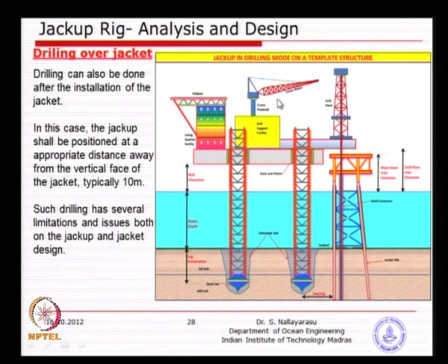So that is where, invariably, if you have a 15 meter reach, you will see that this location will become 6 meters, because you will occupy half the leg size plus the cantilever and all those things. Finally, the clear distance available between the pile and the leg could be only 5 meters, 6 meters, 7 meters, not very large. So invariably you will see that the soil has been disturbed, remolded, strength reduced, and basically the pile design becomes a problem. But even before, when you are actually placing it, what happens?